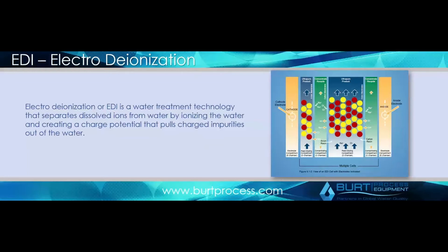So one of the things that came up in the last 20 years is electro-deionization. With electro-deionization, there's no actual resin or chemistry to it. What you're essentially doing is using electricity to pull the ions out of your water. You're passing your anions and cations, your calciums, your chlorides, things like that, and using a cathode and an anode, you're pulling the ions out of the water. This is good because you don't have any actual downtime or chemicals involved, and to some degree, you can control, based on sizing and current, what your end result will be.